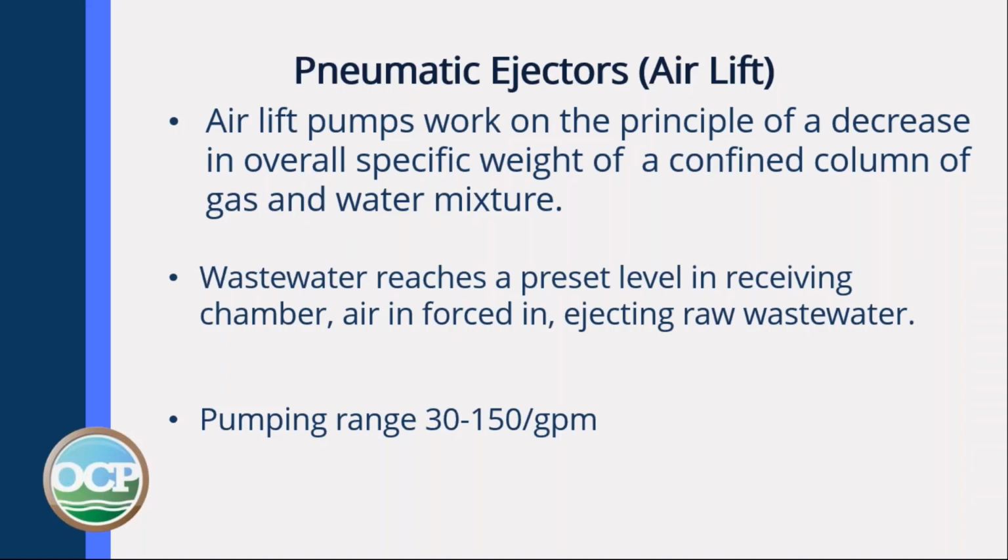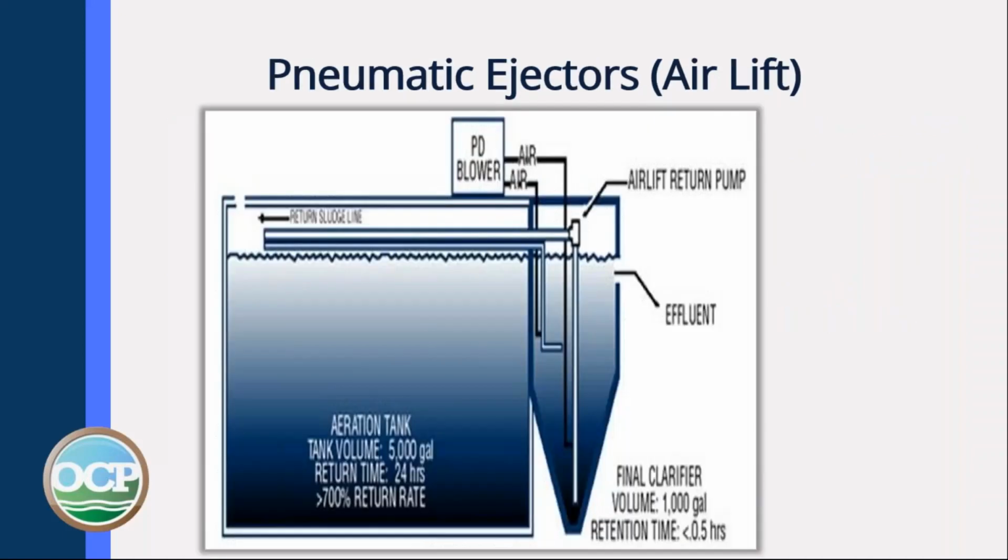And as I said, they pump between 30 and 150 gallons a minute. There's a picture of a pneumatic airlift. Water comes into that chamber there. When it gets to a certain height, air will inject into that section and force the water out.